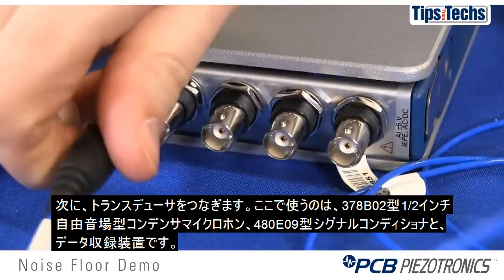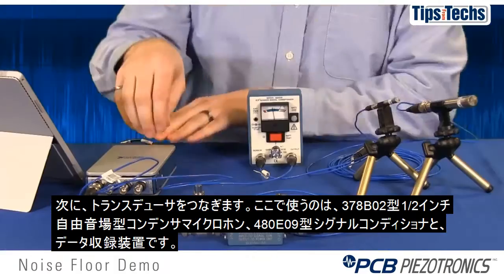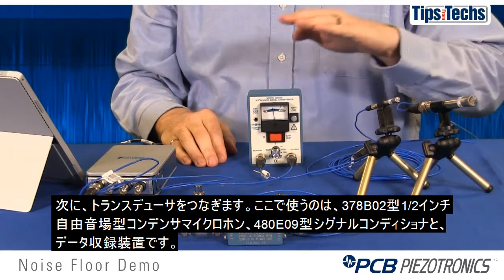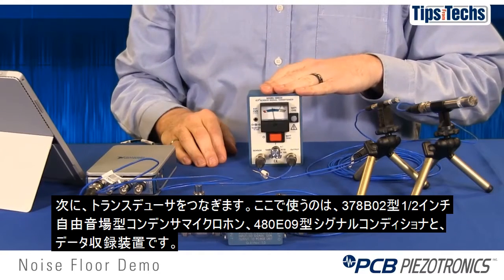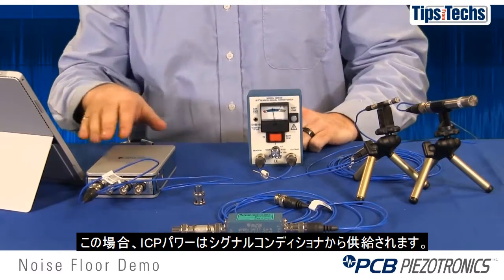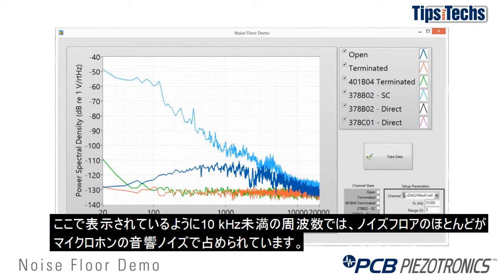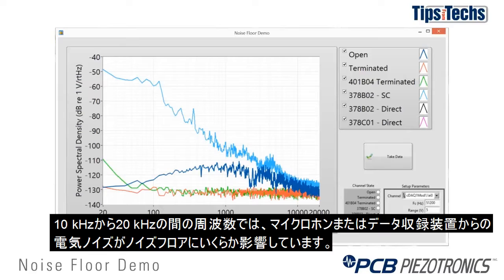Next, we can plug our transducer in. What we'll be using here is the 378B02 half-inch free-field condenser microphone going through our 480E09 signal conditioner and into our data acquisition system. So the ICP power is being supplied by the signal conditioner in this case. Now we see at frequencies below 10 kilohertz, the entire noise floor is dominated by the acoustic noise that the microphone is picking up. Above 10 kilohertz, from 10 to 20 kilohertz here, you can see that the noise floor is now somewhat contributed by the electronic noise from either the microphone or the data acquisition system.